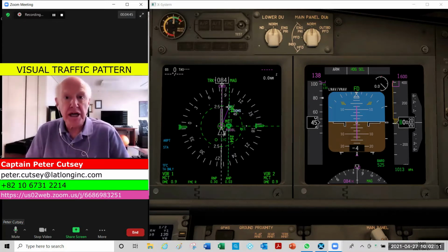We're going to be taking off with flap 1 at TO2. We're going to select flaps 5 and maintain flaps 5 speed at 800 feet. We'll maintain flaps 5 throughout until we configure for the approach and full stop landing.